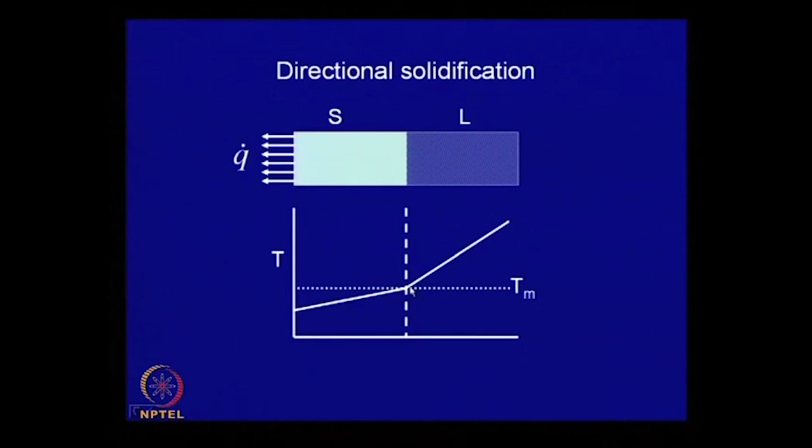In the solid, at the solid-liquid interface, the temperature is the melting point. Outside, you can control the temperature. This is at your control, and you can control the heat extraction rate. So, this temperature gradient will determine the heat extraction rate, and therefore the movement of the solid-liquid interface will depend on how fast the heat can be extracted and flow through this growing solid layer.